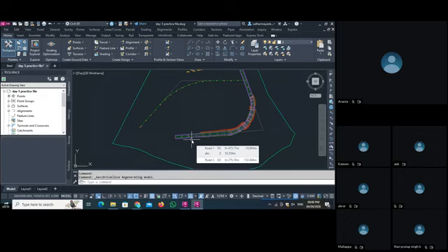For example, if the road length is 1000 meter and I give the total 20 meter of interval, then total cross sections that created is 50. So you have this little calculation in your mind, so you can visualize this properly. So let's create the sample line first. Then I make you understand about the cross section.